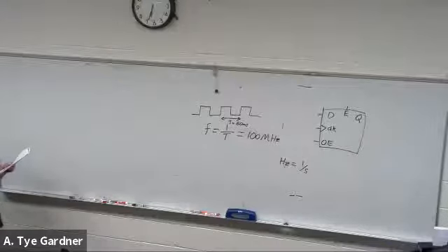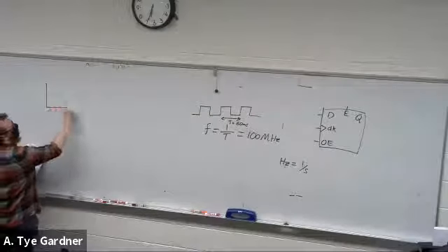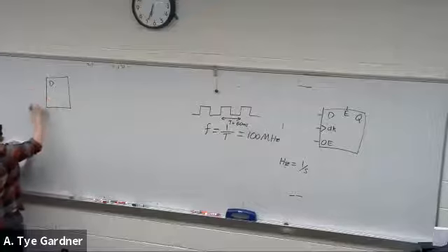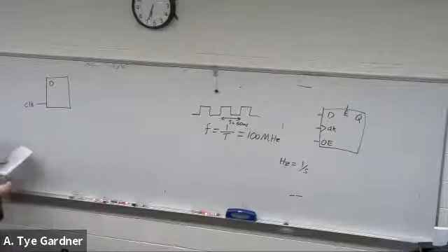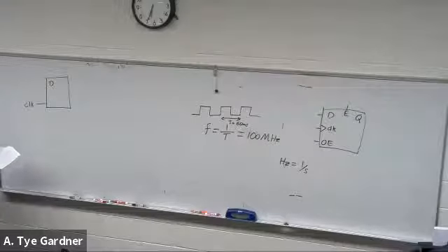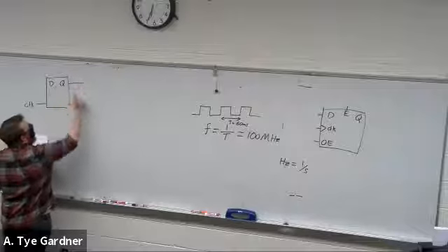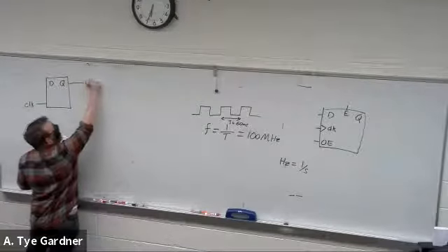Sorry, I'm just making sure I don't miss anything before I jump into this next bit. You can do some kind of interesting things with it. So let's go ahead and have this D flip-flop. And it's going to be clocked at some rate, right? And we want to have this Q output be a new clock.